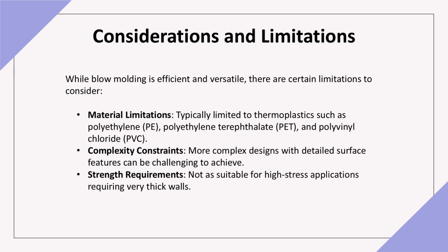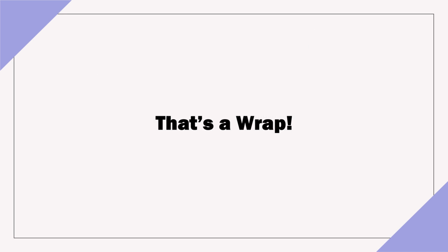However, there are some limitations to consider. The process typically works only with thermoplastics such as polyethylene, PET, and PVC. Complex designs with detailed surface features can be challenging to achieve, and it's not ideal for applications requiring very thick walls. We've reached the end of this video.